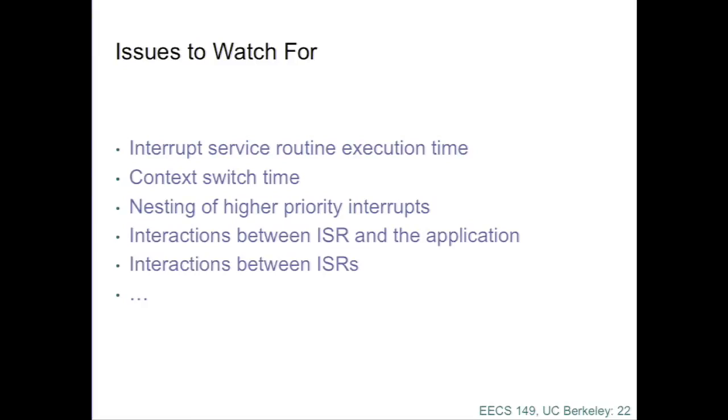You need to worry about nesting of higher priority interrupts. You need to worry about interactions between the interrupt service routine and the application, and interactions between interrupt service routines. And by the way, bugs in this kind of code are far and above the most common cause of crashes.